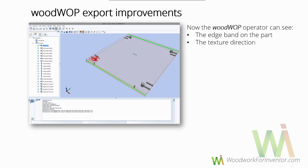So you get those CNC programs automatically, and you get all the data which helps you to position the part correctly. The next important point is the grain direction. This indicator in the center of the part shows you that the texture goes along the same direction as the edge banding in this case. Moreover, in the left-hand corner we see a processing stage indicator, which can tell you about the stage of the processing. For instance, the part can be placed in the CNC machine with the edge banding, without edge banding, with oversize or without oversize, etc.